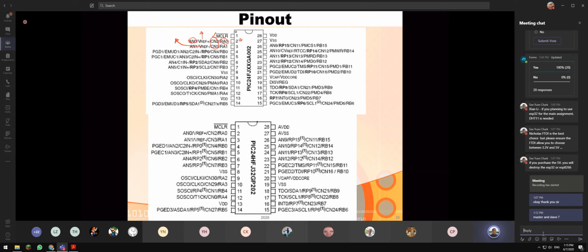So it means that change notification can be high to low, and I can trigger the interrupt. Low to high can trigger the interrupt. So what does it mean? Change notification means that you can trigger the interrupt if there is a transition, from high to low or low to high. Okay, is it all right? This is a very simple explanation.